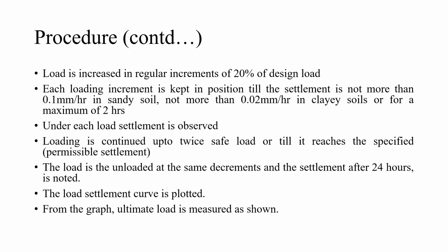Okay, so if you are giving one particular load, we have to keep it steady till the settlement is not more than 0.1 mm per hour in a sandy soil and not more than 0.2 mm per hour in a clayey soil, or till the settlement remains constant for 2 hours. Under each load, after this procedure, we can increase the load.